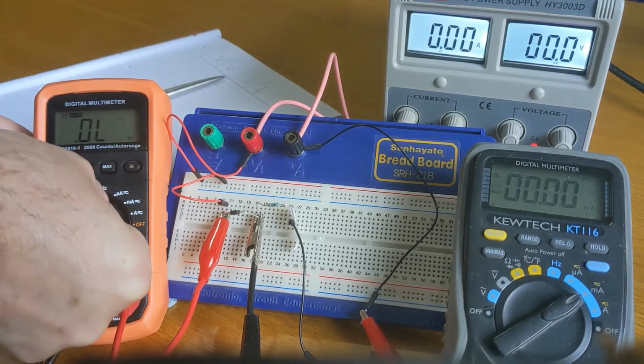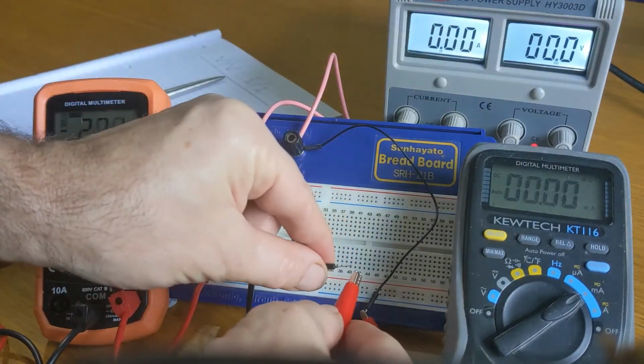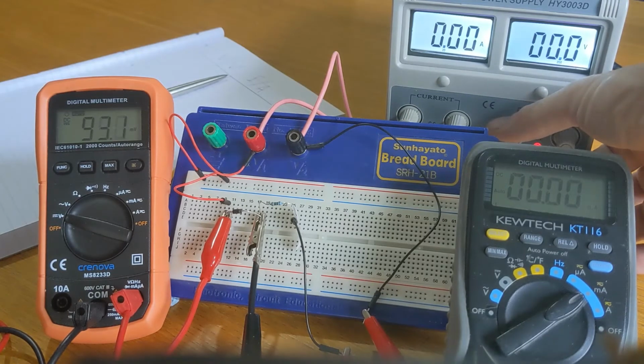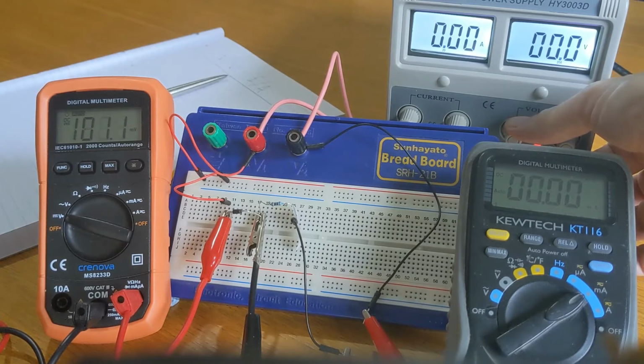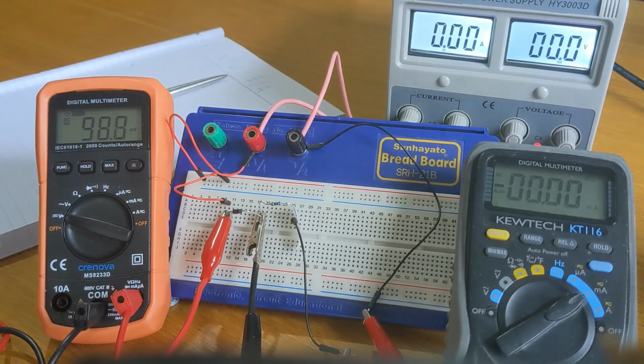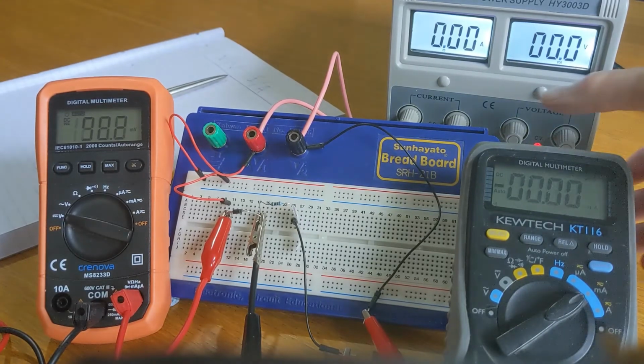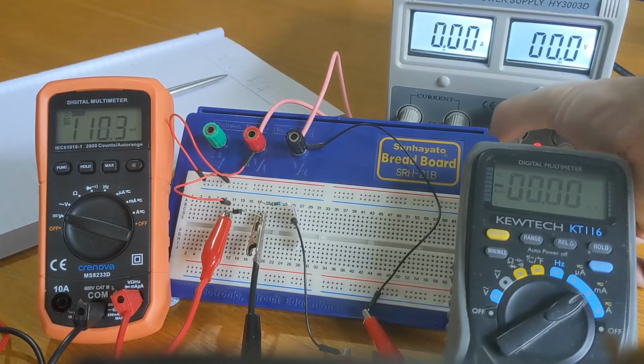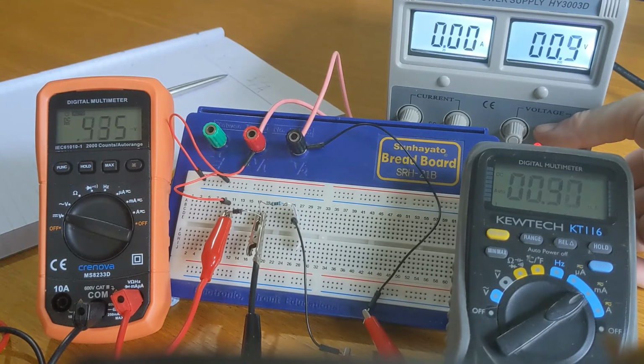Let's now start taking the readings in forward bias. So let's complete the circuit and start to increase the voltage, to start with 100 millivolts, or as close as we can get it. As you can see on the left, the voltmeter reading is being adjusted. On the right, on the current, you will see that there is 0 showing. There is 0 milliamps. At this low level of voltage, we're not going to get any current.